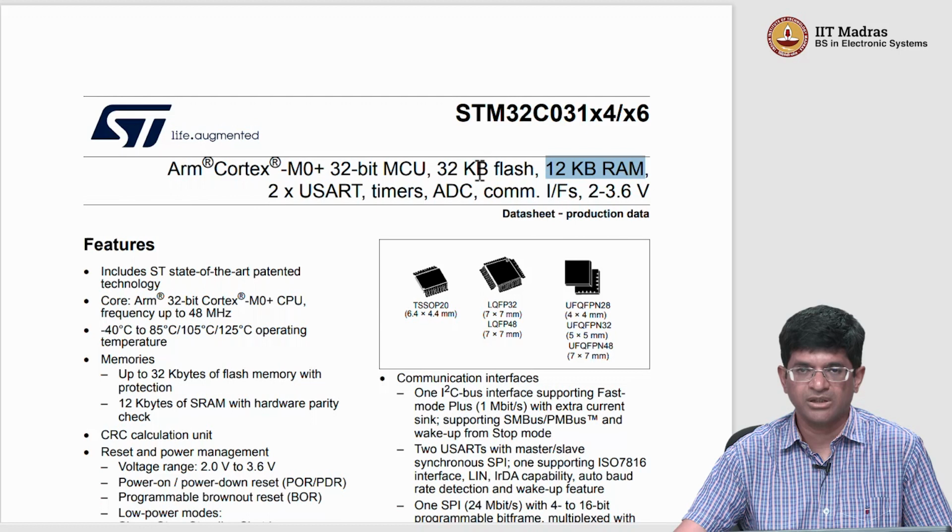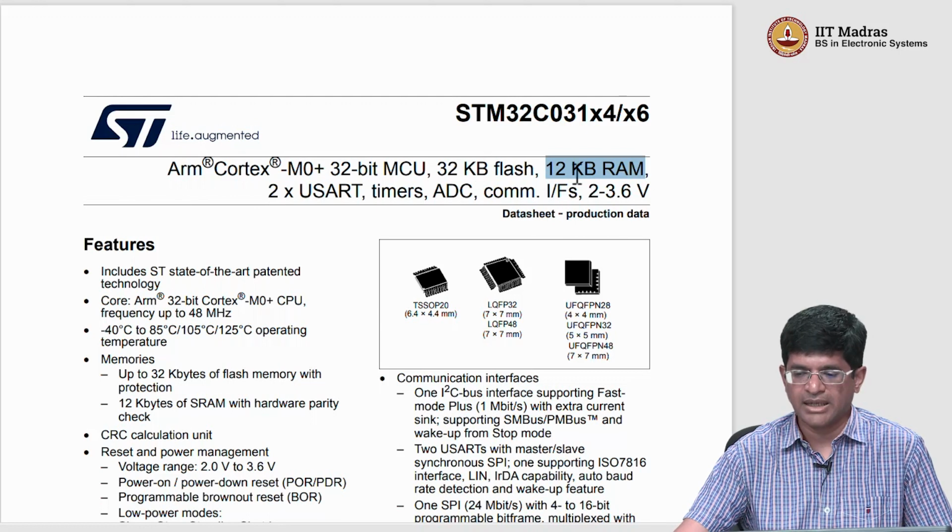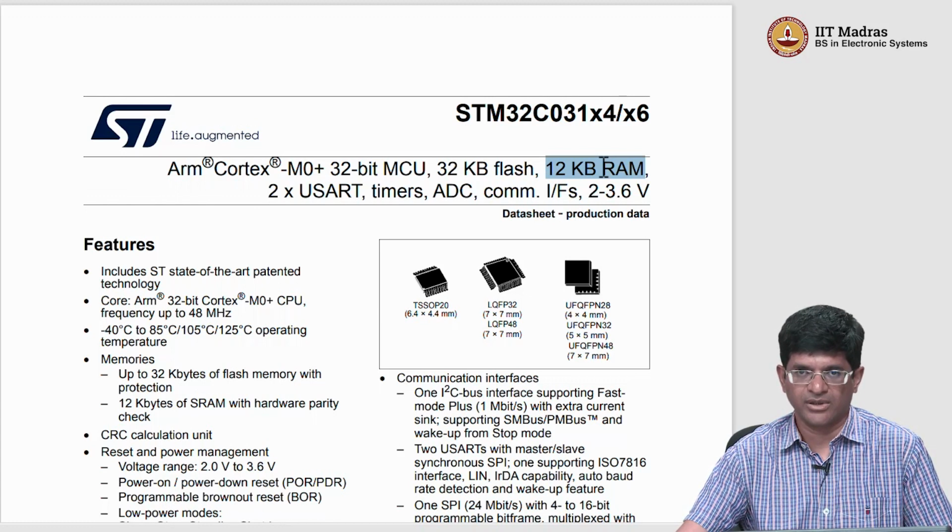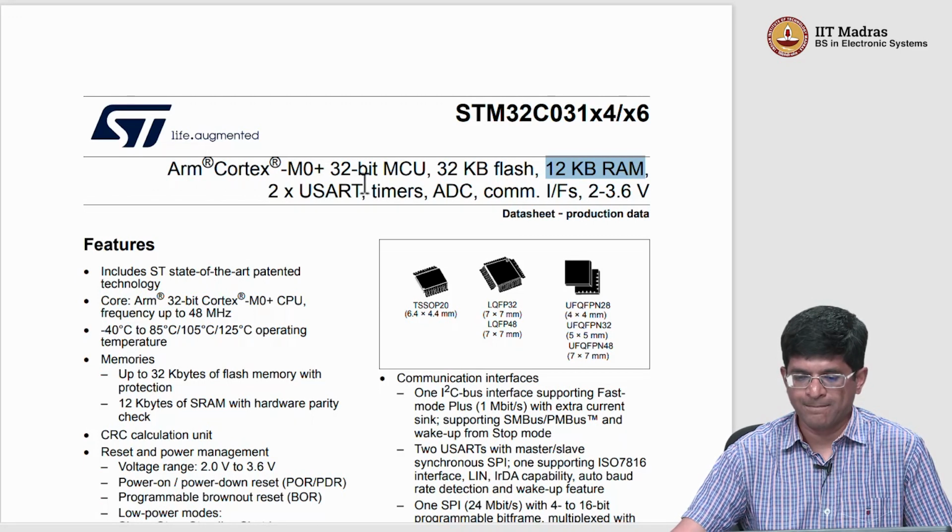Interestingly, you can have a larger program and a smaller amount of RAM. The RAM is used for the actual running of the system, right? All the variables, the temporary storage, the program needs to get loaded into RAM and then run from there. So the RAM is what finally determines what can run at the actual execution time. The flash can be used for storing additional information, the configuration, the actual program or parts of it, which get loaded as and when necessary.